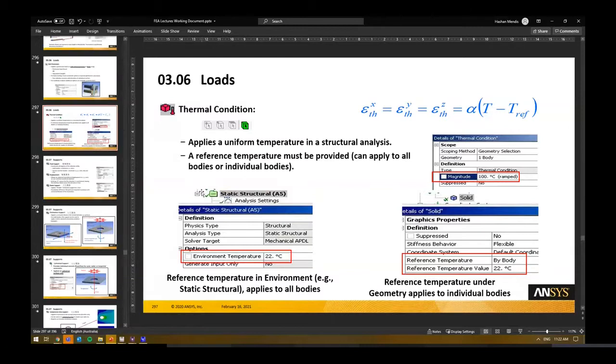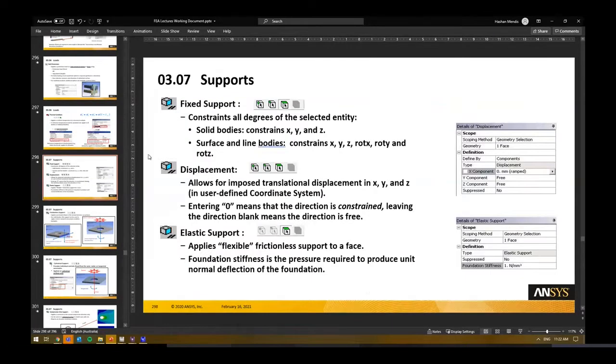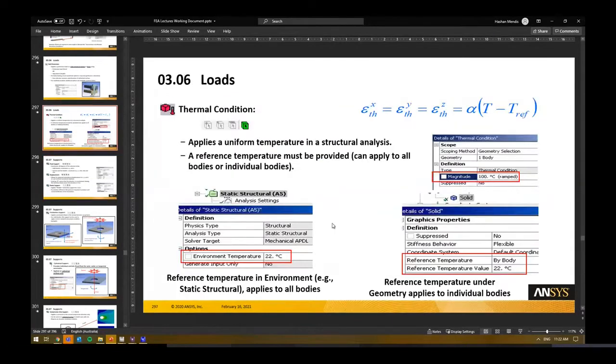So you want to think about that stuff. And again, these are particular to your problem, right? Depending on what you're interested in, it always comes down to what is your main area of concern. If it's specifically about how the bolt and nut interact, then you want to model the threads and all that. But if it's just a small part and you just want to make sure load gets transferred from component A to component B, you can make some simplifications, right? So that's what we want to think about with the loads.